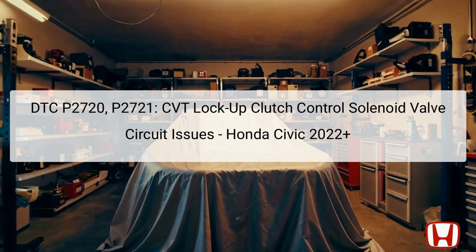Conversely, the P2721 code signals an overcurrent issue, meaning the TCM detects excessive current flowing to the solenoid for a similar duration during activation. Both codes highlight critical issues within the solenoid valve circuit, which impacts the transmission's ability to effectively engage the torque converter lockup clutch, leading to potential erratic shifting and reduced fuel efficiency.